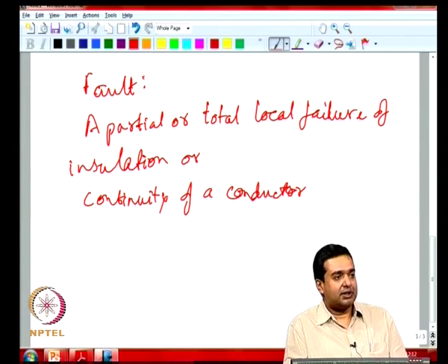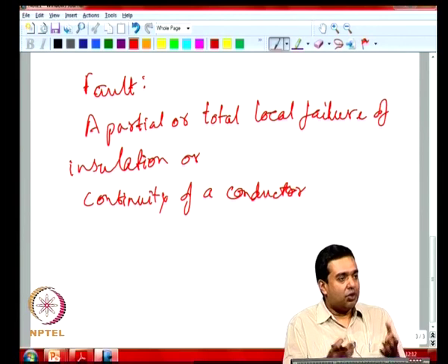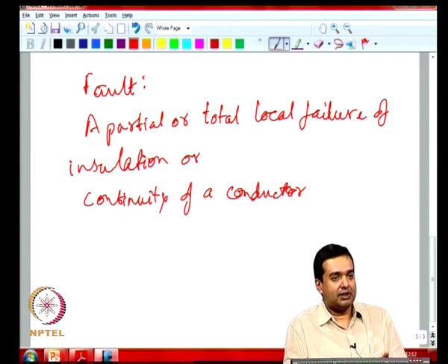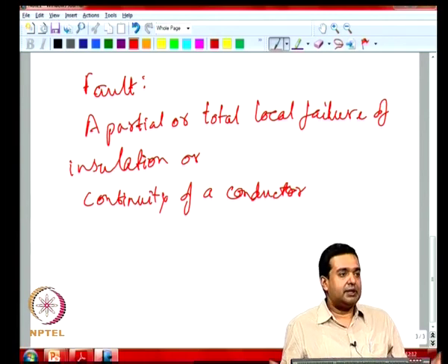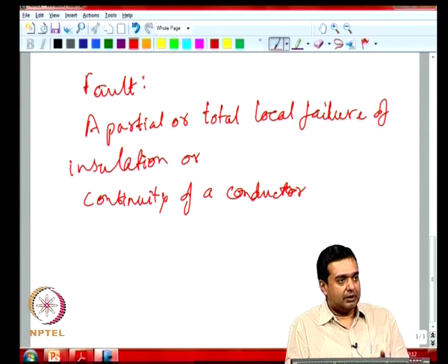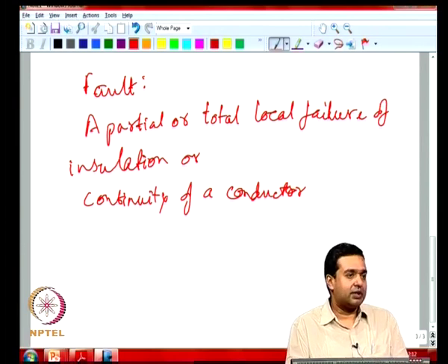and once you have a short circuit, then essentially what people would see is the voltage collapsing rather than over voltage. So, in the immediate neighborhood of the lightning you might see an over voltage, but further away in the system what you would see is under voltage, because you now have lines that are arcing over and then an upstream breaker would open.